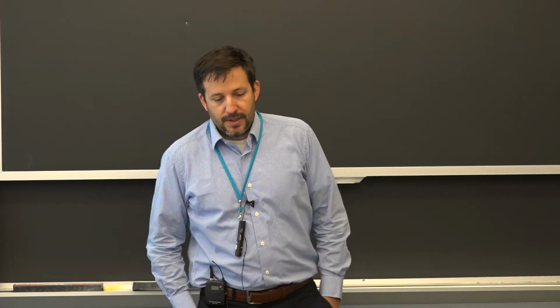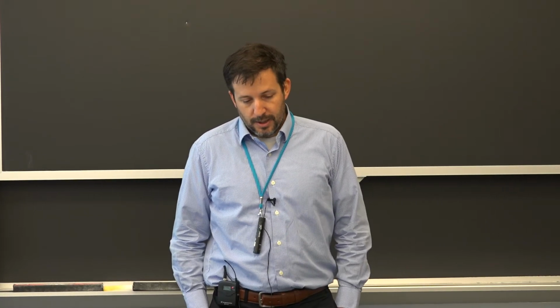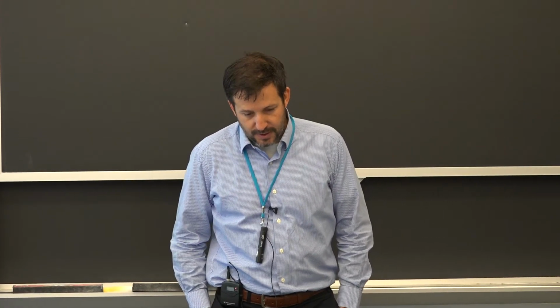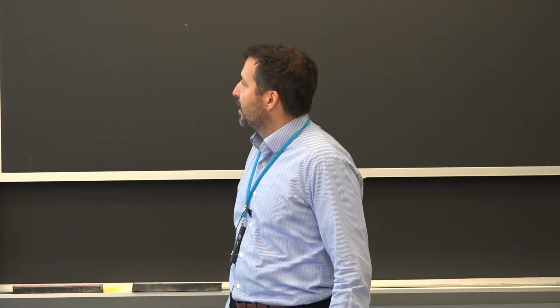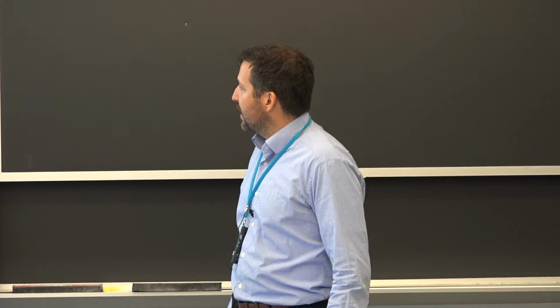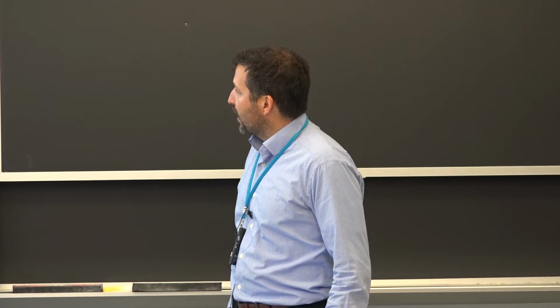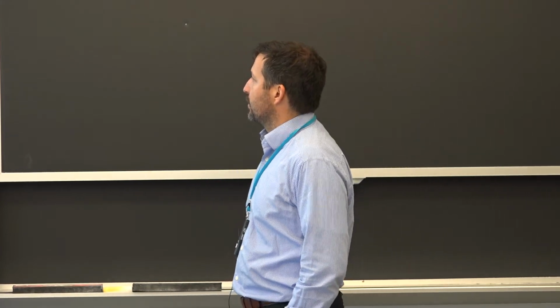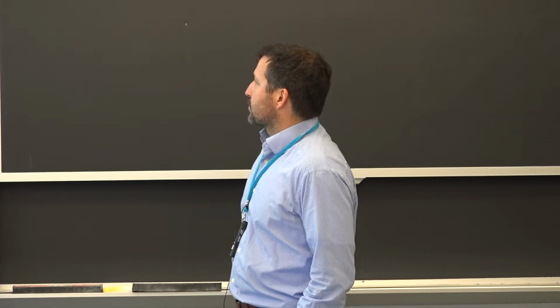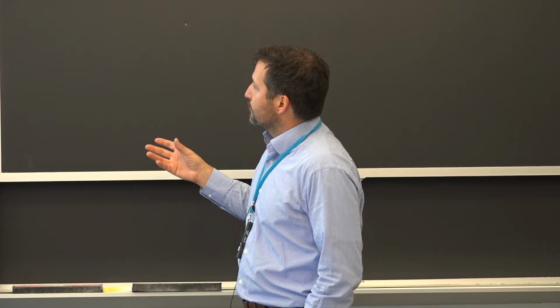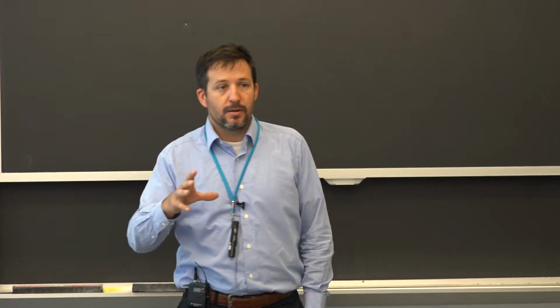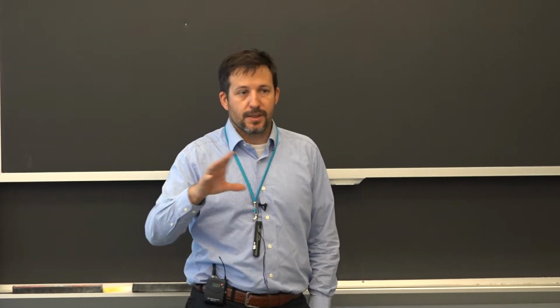So in the case of the Liberty Tower, they used copper rivets, and they used this copper saddle here that you can see is essentially making the tie between the armature of the skin that was wrought iron back then, so not even steel, and the entire assembly here. So you have this clamp that is small and is nailed from one side to the other. It's connecting two structural elements, and you do want it to not corrode preferentially.